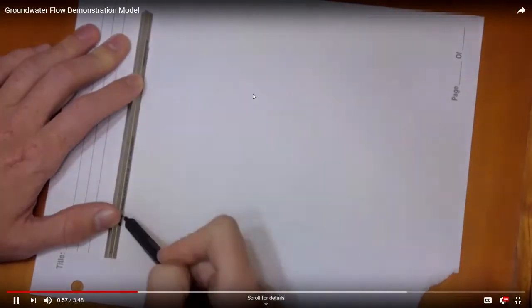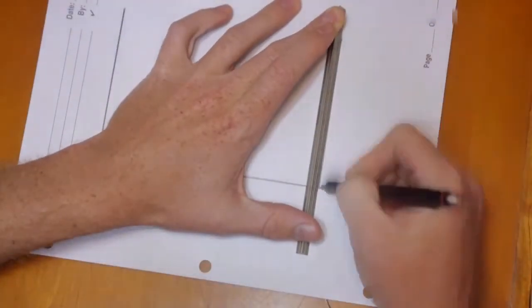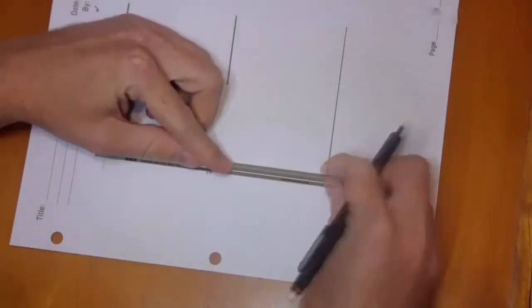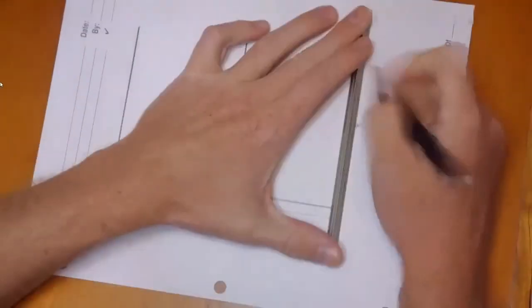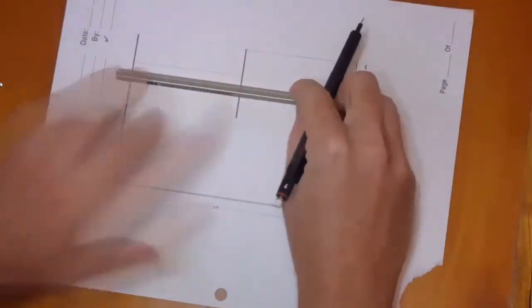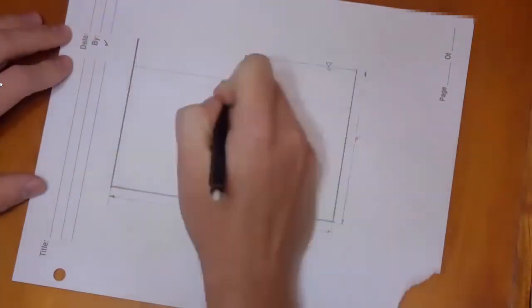It's often important to be able to characterize the flow of groundwater. Water in the subsurface can have a major impact on civil structures by causing uplift pressure, seepage, and changing the strength characteristics of soil, among other things. We have fancy computer models that do a good job simulating groundwater flow now, but even today one of the most important tools used by geotechnical engineers is the flow net.